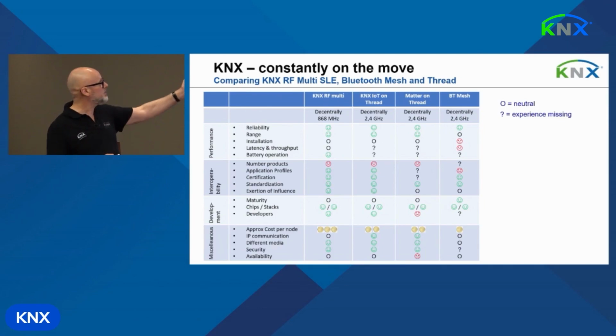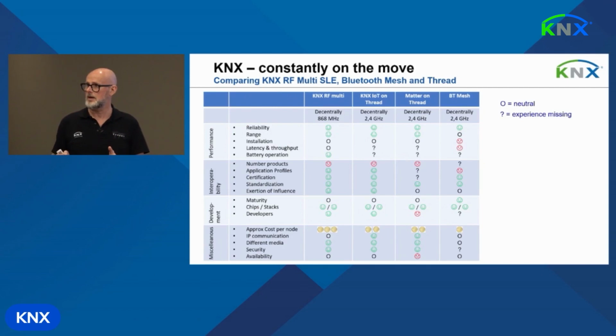So, well, the big difference, of course, lies in the frequency that is being used. So we use 868 megahertz and 2.4 gigahertz. Physically, this already allows us a larger range than 2.4 gigahertz alone. The drawback of 868 megahertz is the fact that it may be regionally limited, and you may not be able to use it as a manufacturer on another market than, for instance, Europe.